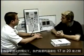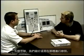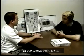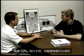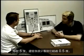In an engine out situation, it's between 17 and 20 degrees we want anyway, so we might as well just run the trim over there. In an A319, we can get up to 30 degrees trim, and so that'd take approximately 30 seconds to get full rudder trim. According to the UAL flight manual, it says that the autopilot can provide 5 degrees per second, although I rarely see it go much more than 0.5.